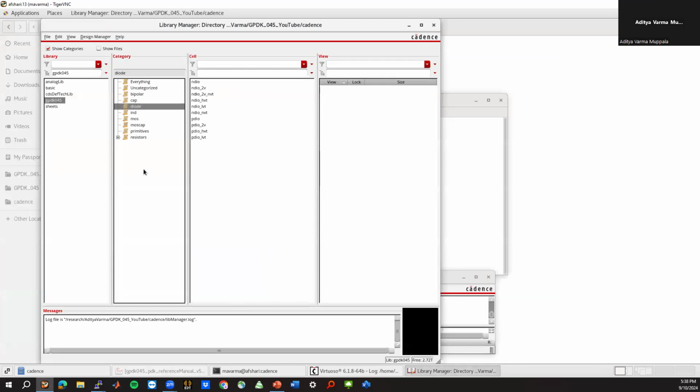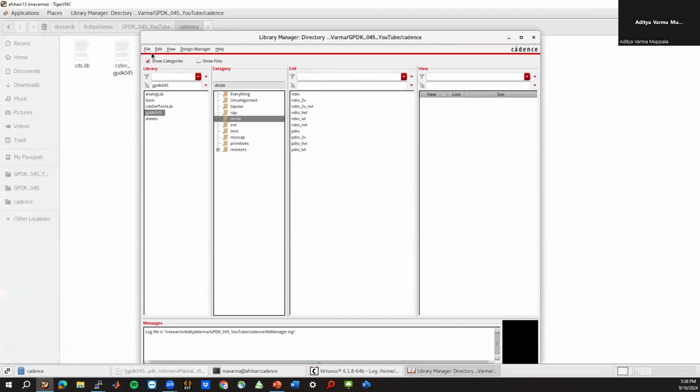So now that we have that going, what I can do is maybe do a very simple simulation of the fmax of this process. That's the first thing you should simulate when you start a new process, especially when you're doing millimeter wave circuits. So what we'll do is create a new library.